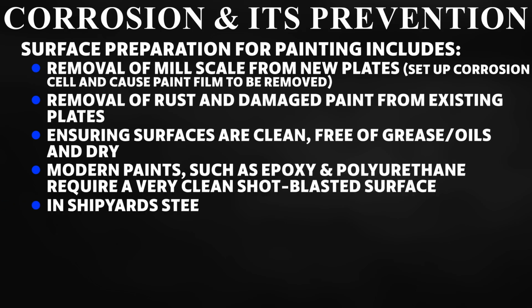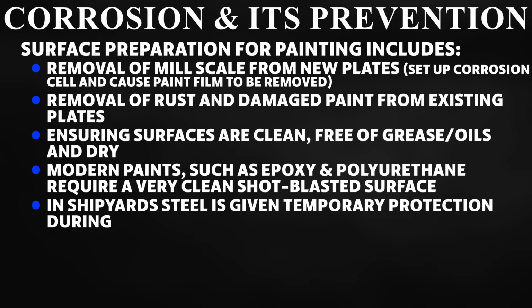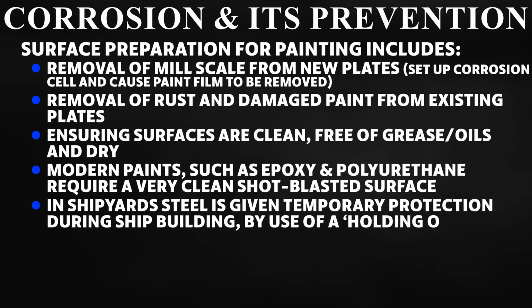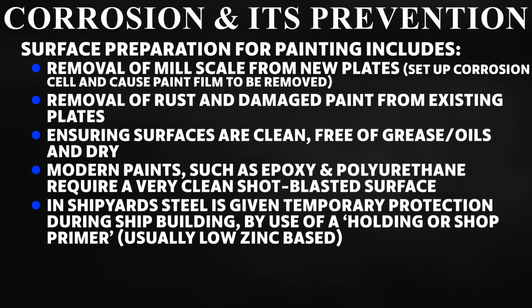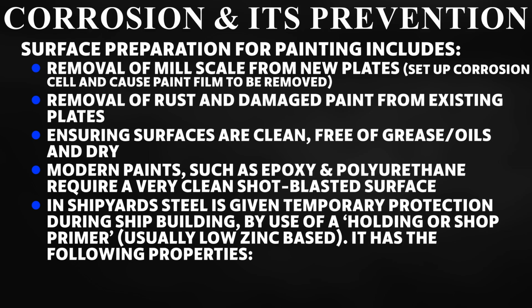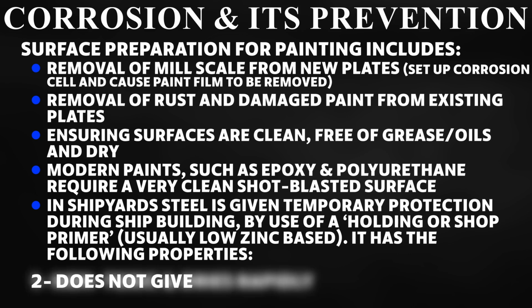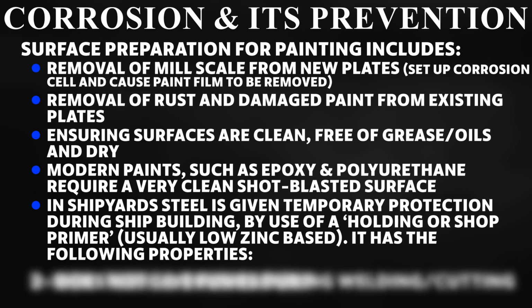In shipyards, steel is given temporary protection during shipbuilding by use of a holding or shop primer, usually low zinc-based. It has the following properties: 1. Non-toxic and dries rapidly. 2. Does not give fumes during welding or cutting. 3. Is compatible with other paints.